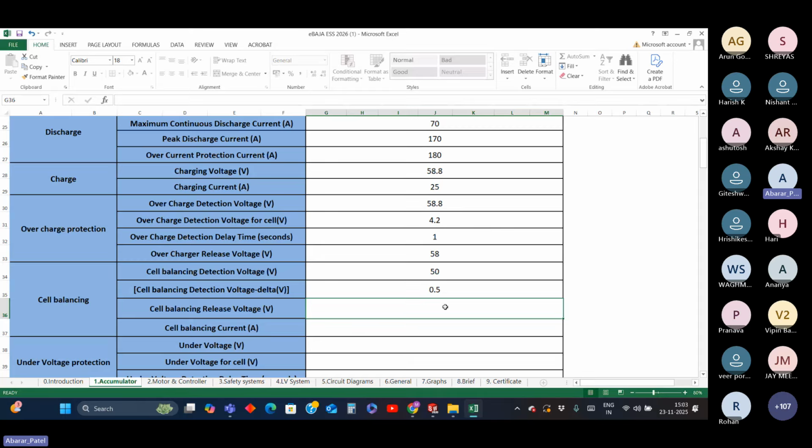And so generally, what BMS does is it calculates this delta by measuring the voltage of the cell, and then it tries to balance. It tries to push a small amount of extra current within the cell to ensure that the cells are balanced and maintained at equal voltages. There are two types of balancing, if you might be aware of it, active and passive balancing.